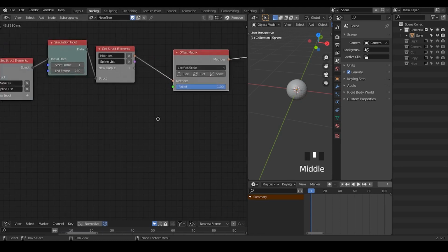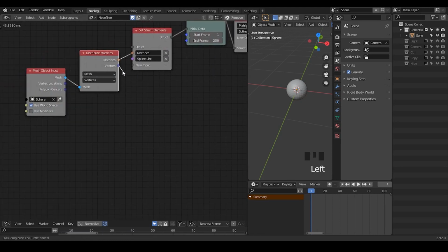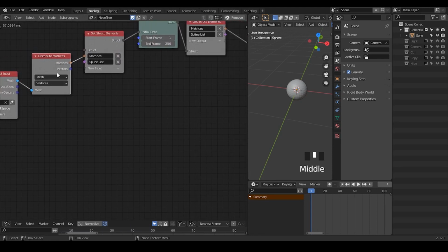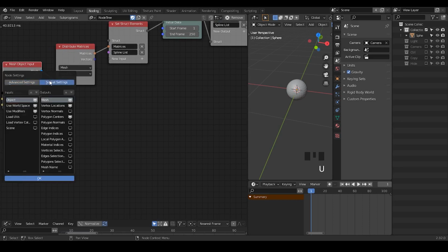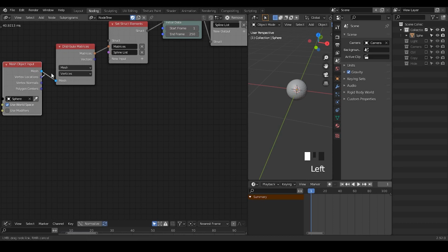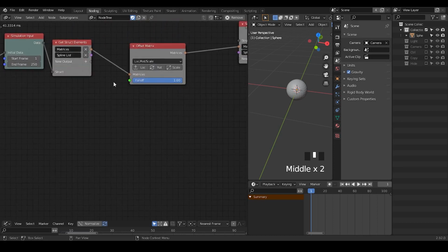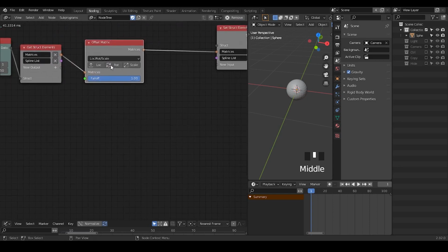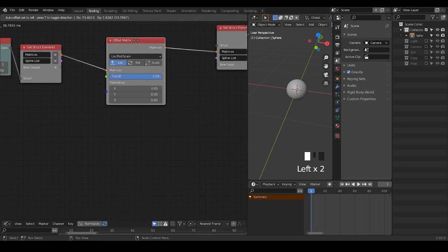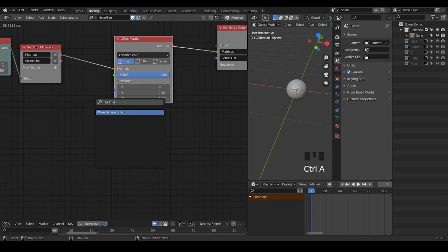The reason I'm inputting matrices instead of a vector, which is what people usually do, is because these matrices include information like the normals of our mesh, so that I can input a single value instead of two values, vertex locations and vertex normals. So use one value to store two values. In this case that is what I need. Although in the simulation node we need to do some conversion, I think it's fine. And then I'm going to use the Perlin vector noise.